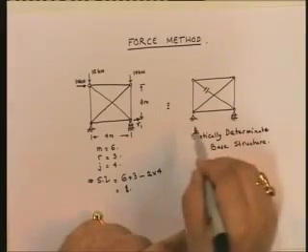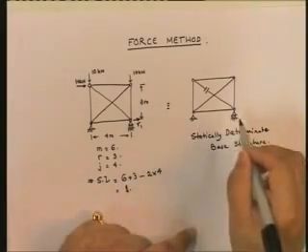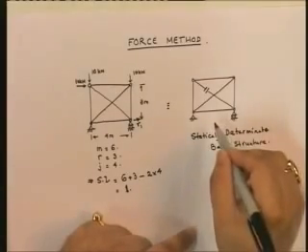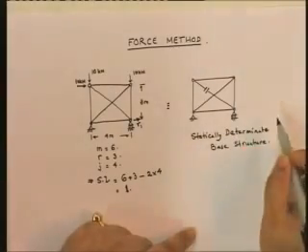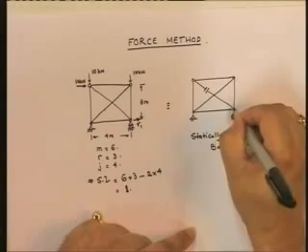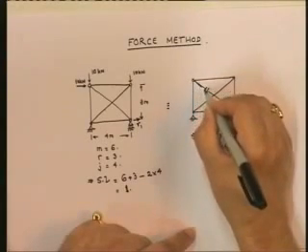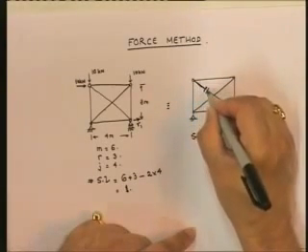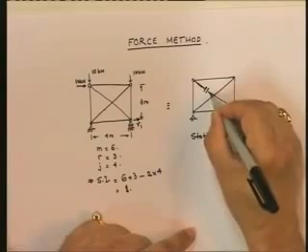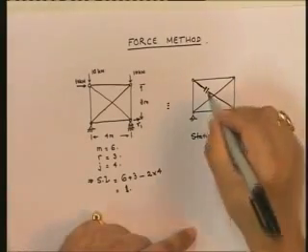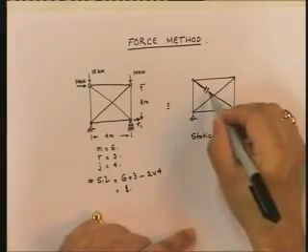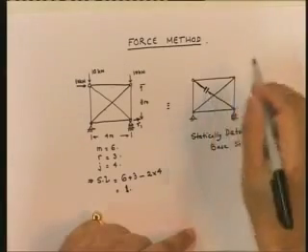Once you eliminate one of the unknown forces, now you have a statically determinate structure, because if you look at it, suppose in this particular case, what have we done? We have cut this member. Once we cut this member, what happens? We know that the force in that member is 0. And since we know the force in the member is 0, let's look at it.